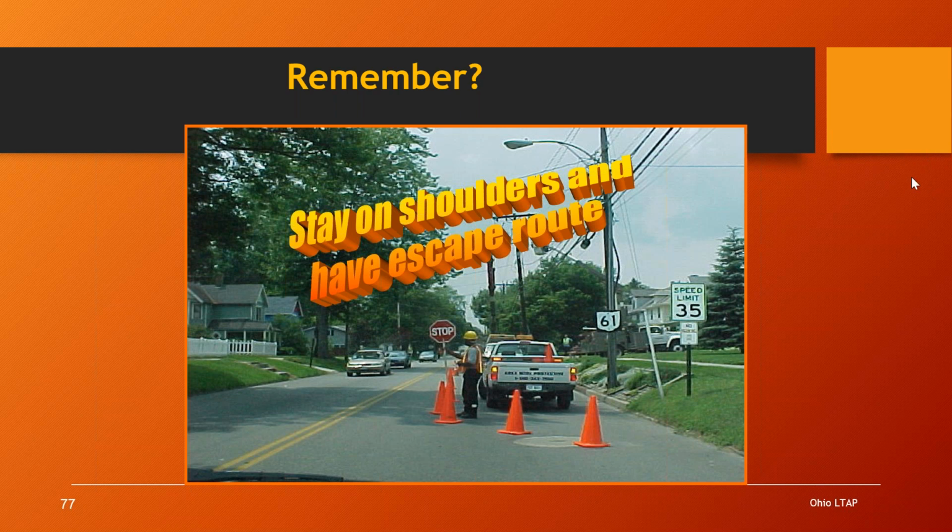How long can contractors leave signs up after work is complete and they have left the area? We have contractors that leave signs up all night. Well, preferably if the road is open, then the signs are gone, because we don't like to mislead the public. Maybe there's a special meeting to have with the contractors when they're getting close to getting the job done, or have a paragraph in the notes page of the plans that talks about when to take the signs down.